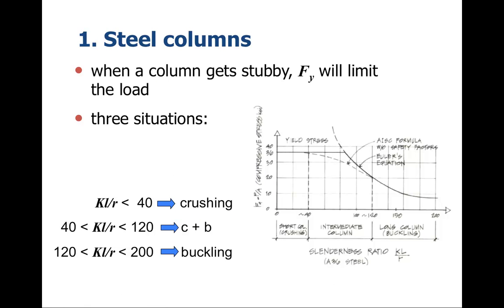All right, some other things related to steel columns. When the column gets short and stubby, F sub y will limit the load, F sub y being the allowable stress in crushing. So we have three situations. One where K times L divided by R is less than 40. Here we have the crushing response, in this particular zone right here.